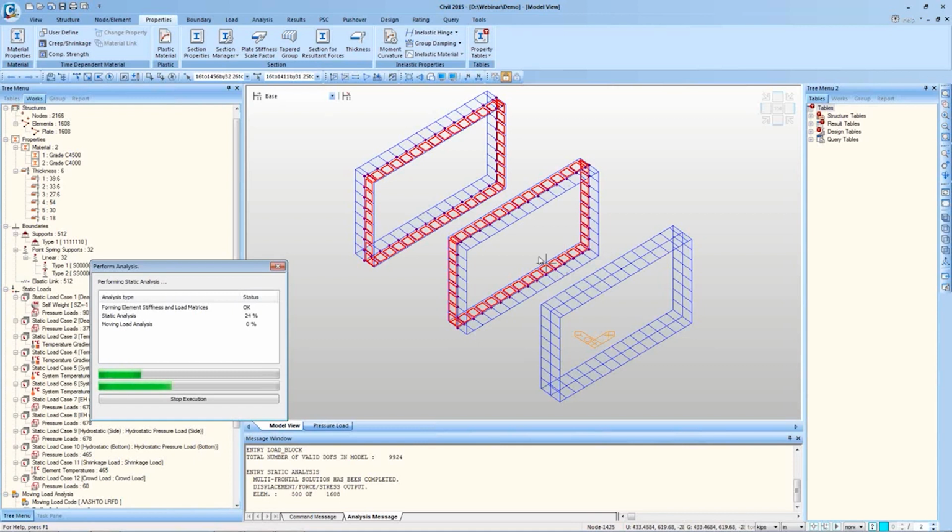The advantage is, for calculating the force at, let's say, I end of first beam, it will use the resultant force of all the nodes highlighted here. And at J end, all these nodes which are selected in second section and I'm moving my cursor on will be considered for force calculation. And these forces can directly be used for performing the design. We'll wait for the analysis to be completed.